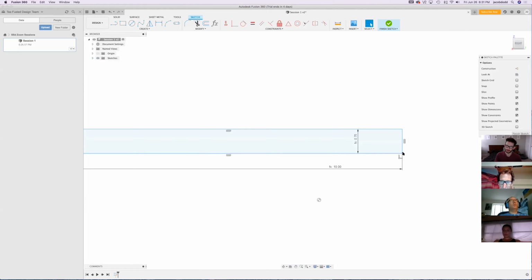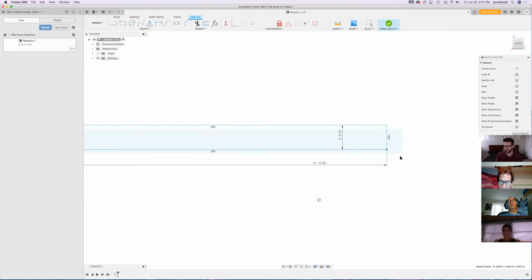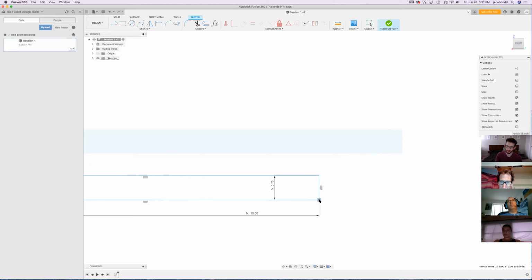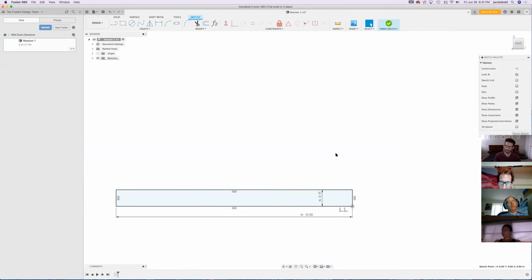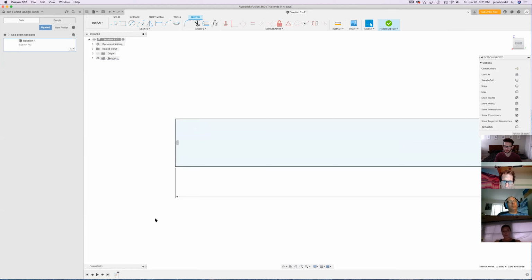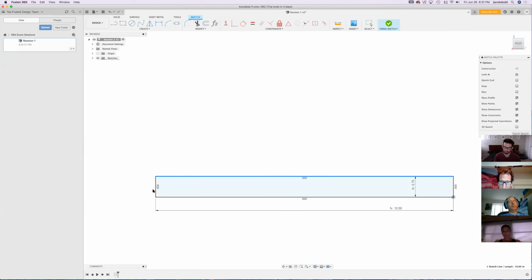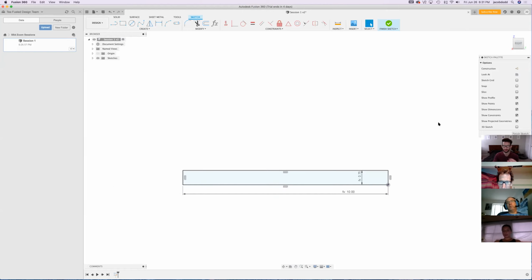So what we can do is drag one of the corners of this rectangle we've made. So click and drag and just kind of hover over there. You see it kind of snap into place with a little blue square around it. And that little blue square means that it's going to be locked onto that point. You see all these lines have turned black now, which means, try as we might, if we dragged it and moved it, nothing, nothing, nothing. So we can't edit this now. It's locked in place, which is what we want. Because as soon as things are not locked down, it means that they can shift and move, the angles could change.